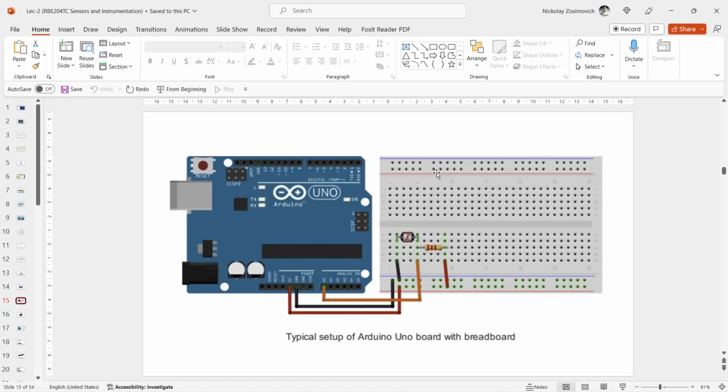So this board consists of an ATmega328P microcontroller by Atmel running at 16 MHz, a small power section with linear 5 and 3.3 volt regulators, and a separate ATmega8U2 microcontroller, which is used as a USB CDC device for programming and communication. A single USB connection can be used for both programming the device, like uploading new programs into the main controller flash memory, and communication with the device.